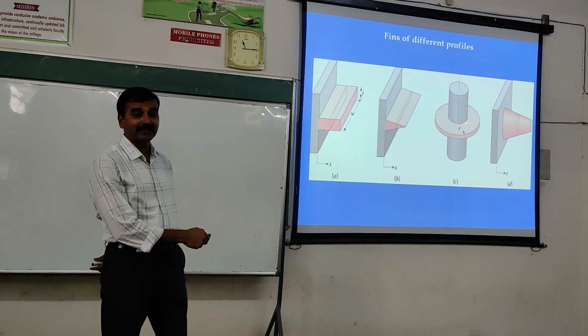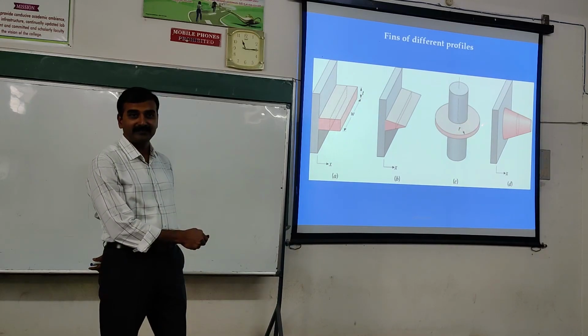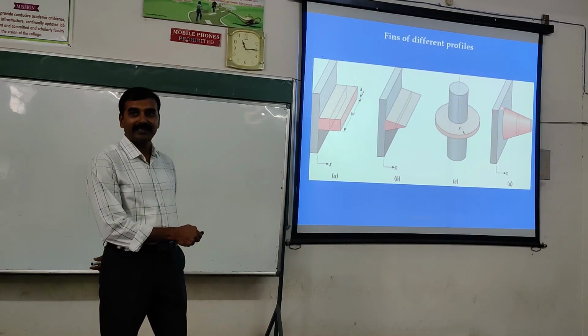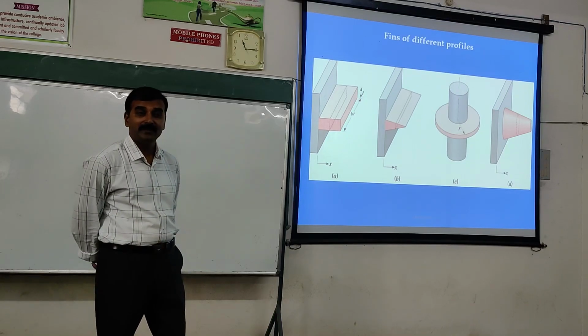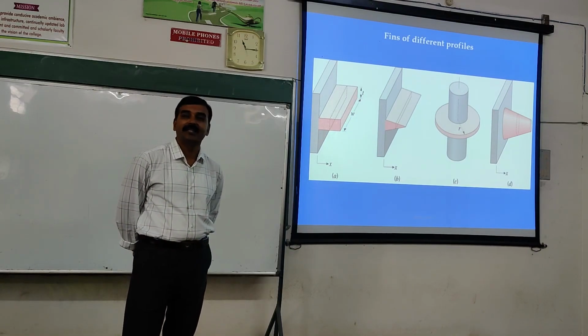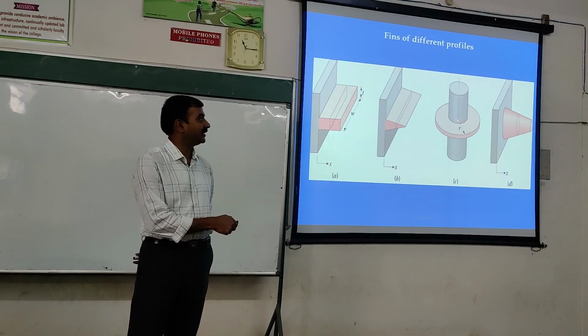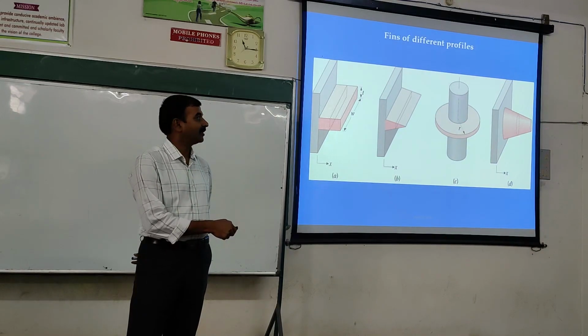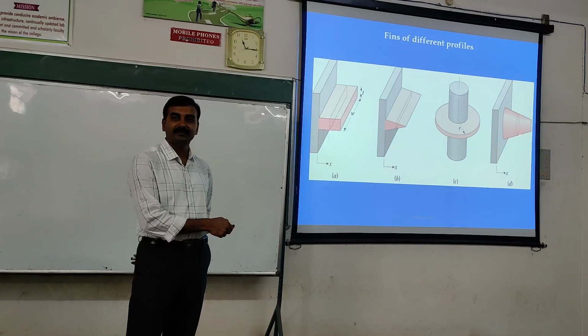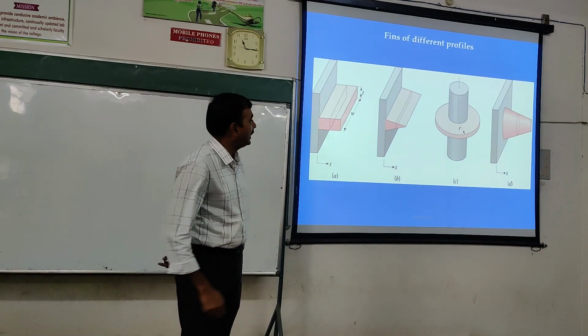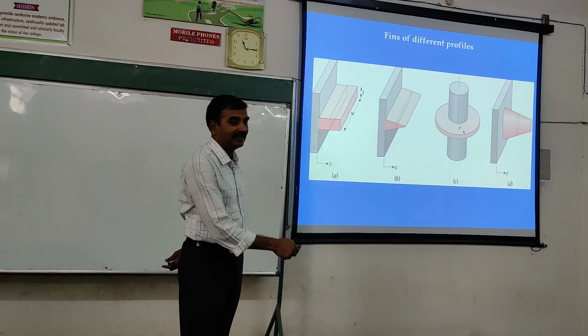If you take this case, is it same or will it be different? In the direction of R, AC same? Same or not? It's not same. Why? Radius is increasing. Suppose if you take section here, you consider only radius up to this point. You move here, radius increases. Right? What about this? Same or different? Different. Varies. Right? So therefore, whatever the formula that we derived earlier cannot be applied to these cases, or cases like this.